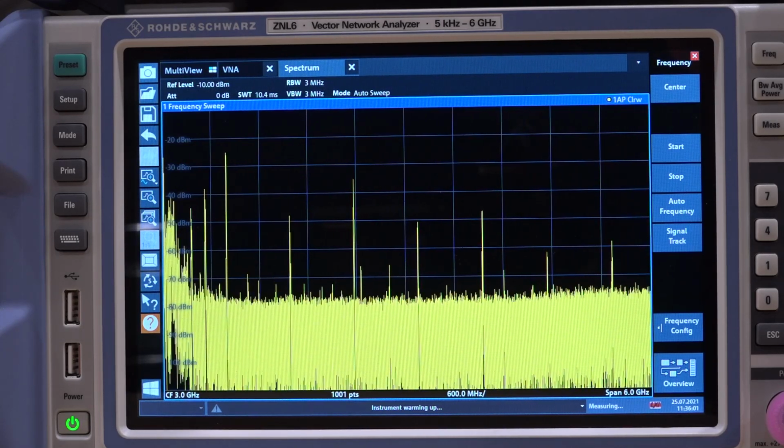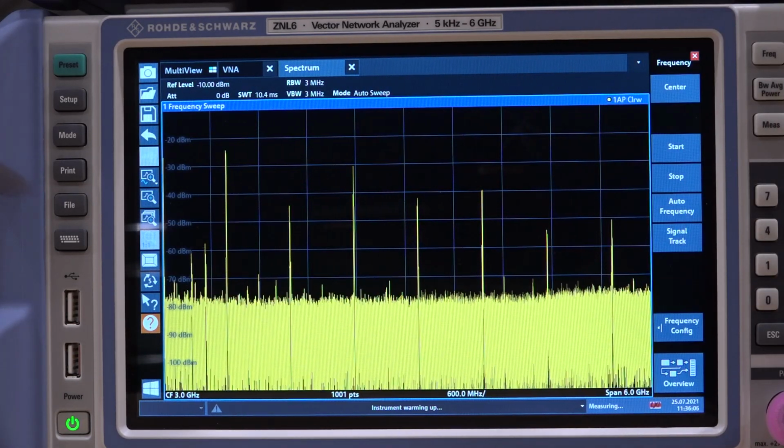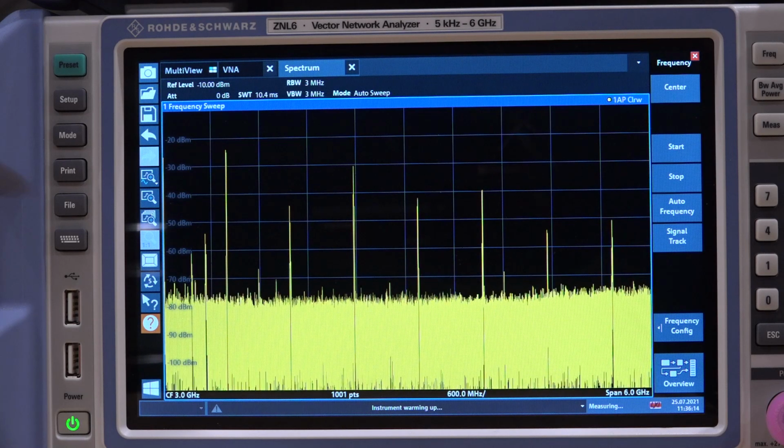Let's go to the output of the divider and see if we see a signal at all now. There we go. There it is, right there. The one next to it is my wireless microphone. You can see if I move it around, the tone goes up and down. But yeah, the divider is now producing. You can see all the harmonics of the divider. It's probably putting out a fairly nice square wave coming out. Looks good. This is very promising.